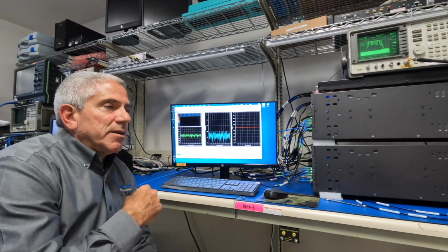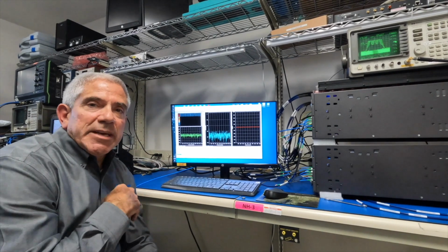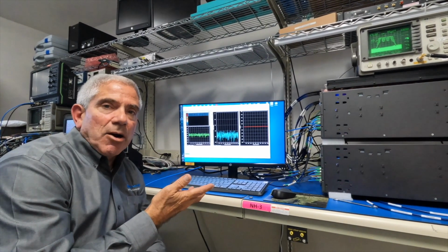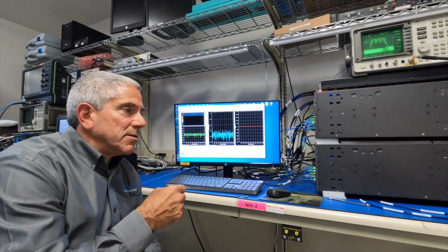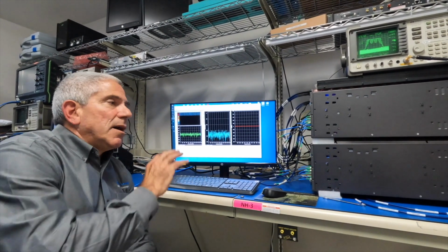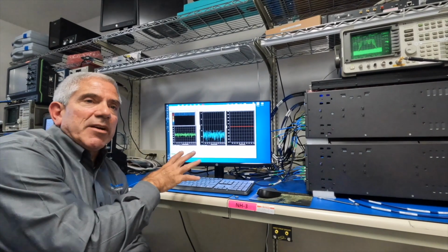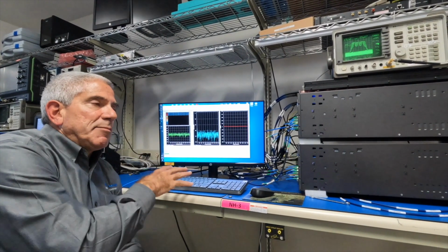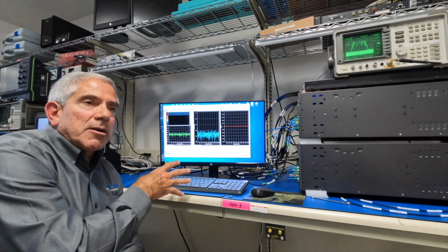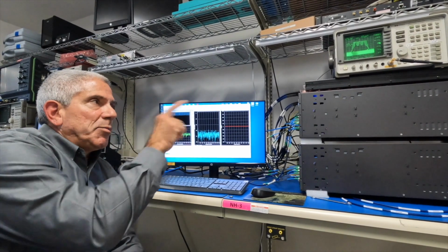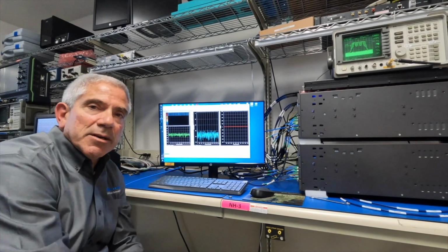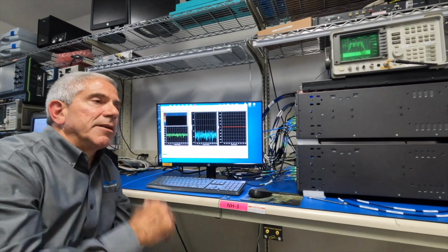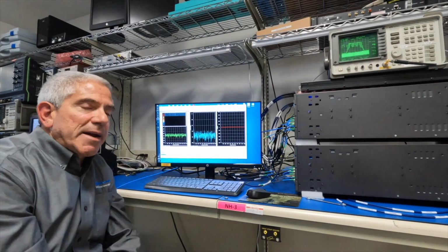But what we'd like to show you is one of the proof of the pudding: can we take the digital signal that was captured and turn that back into RF that looks just like the original? So we'll do that really quickly. The captured file we just did, the 45-second file with the RF off at first, we're going to grab that digital file and play it back with our RF playback and generation system. We'll put it first into the spectrum analyzer to show you that it does in fact line up with what we had put in from the RF threat emulator, and then we'll also show you what it looks like back into the digitizer.